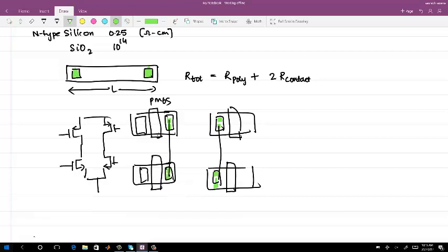So do not neglect this contact resistance in your calculation, provided it is important. If the contact resistance is only 1 or 2 ohm and you are realizing thousands of ohms, then you may not see it clearly. But for differential circuits, make sure that they are differential in each and every respect. Otherwise, you will have asymmetry.